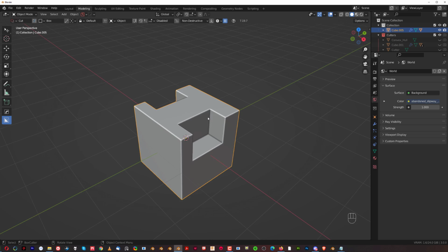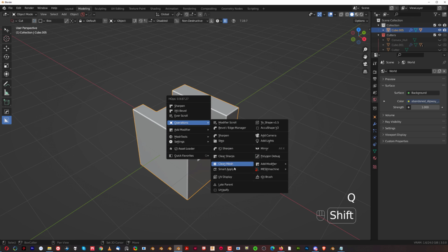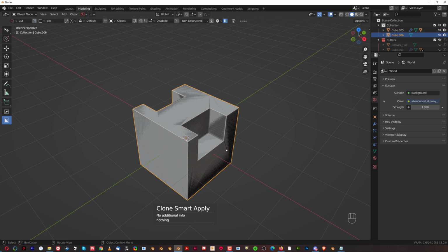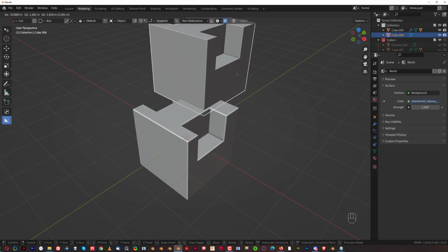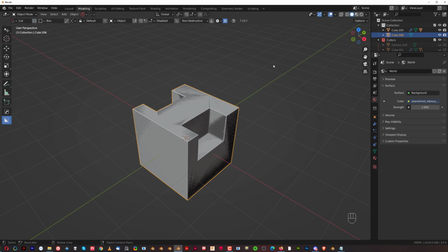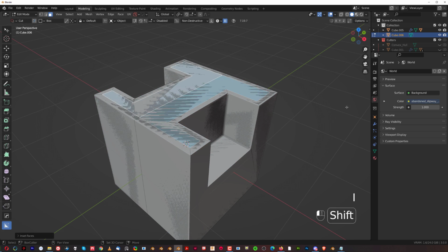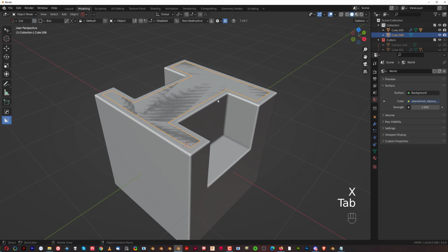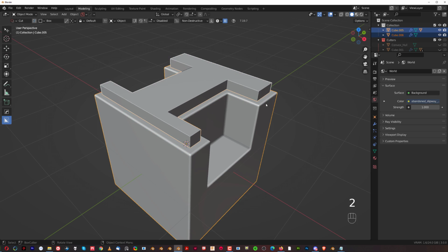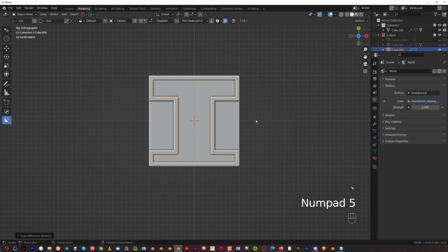A lot of dance. So what I'm going to do is go here, Q, and Shift click on Multiply. It will duplicate that cube, remove all the modifiers, apply the booleans, and I'm going to be left with just this shape. So what I can do now is select this face. I can inset it like this, all right? I can Control I to invert it. I can remove all the faces, grab this top, press Q, Solidify, press 2, Shift click this, Q, and Difference, right? And that's a live modifier on the mesh.